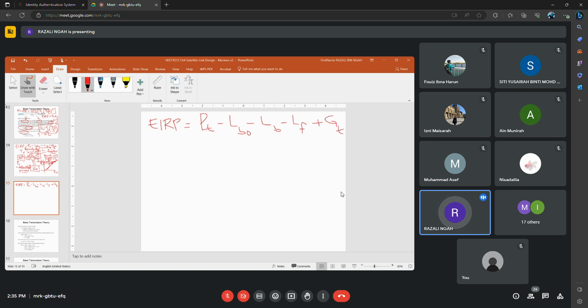So those are the three possible losses from the power amplifier, which contributes PT, until we have the antenna GT. This also considers your duplexer. So these are possible losses. Depending on the question, sometimes branching and feeder loss can be combined together. So it depends on the question.